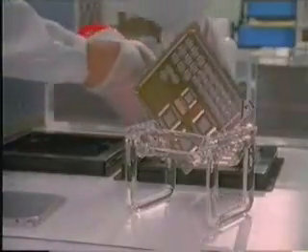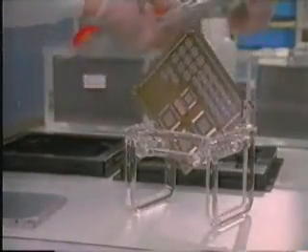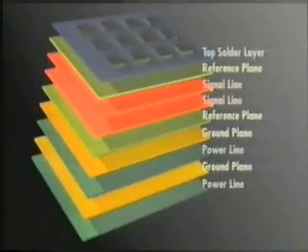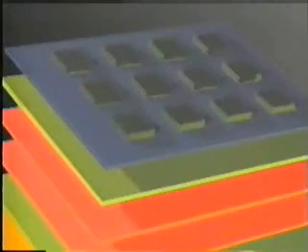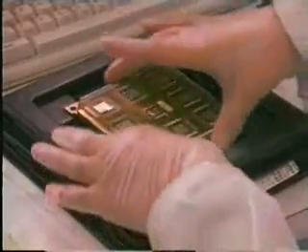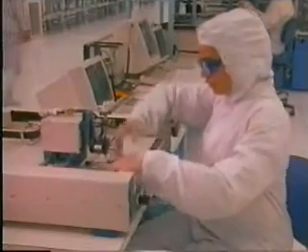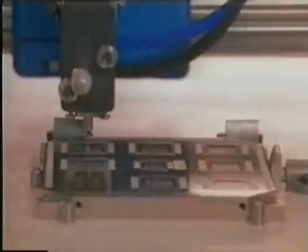The board of the MCU is a high-density signal carrier substrate. It consists of 9 interconnected metal layers, insulated with polyimide coating and fabricated using semiconductor technology. The top layer is used to solder attach all the integrated circuits and connectors. This signal carrier, with its 3,000 to 4,000 solder bonding pads, has been cleaned and prepared for the attachment of high-powered chips.